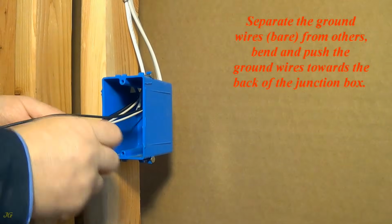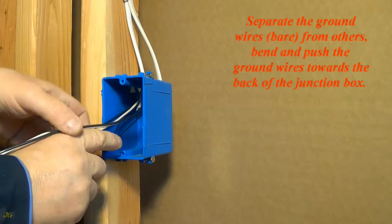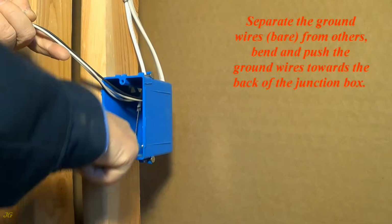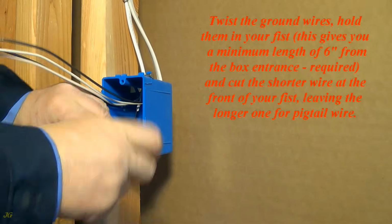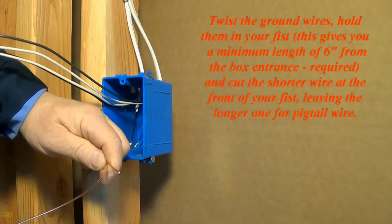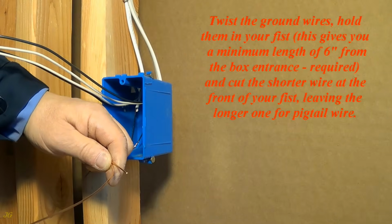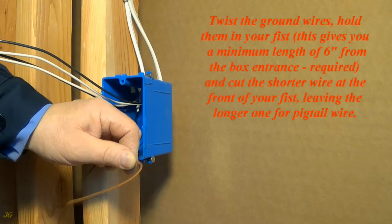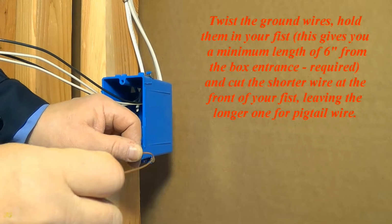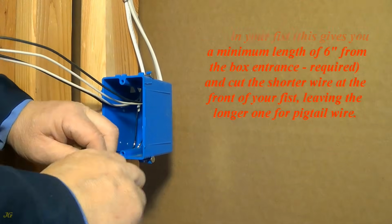Separate the bare ground wires from the others. Bend and push the ground wires towards the back of the junction box. Twist the ground wires. Hold them in your fist. This gives you the required minimum length of 6 inches from the box entrance, and cut the shorter wire at the front of your fist, leaving the longer one for the pigtail wire.